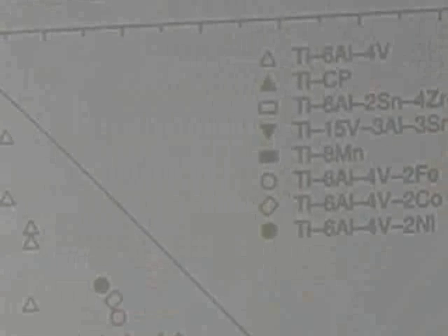So it's harder to get superplasticity in a single phase alloy, okay? But it's easiest to get superplasticity when you have about 30% of one phase inside another, because that 30% phase is completely encapsulated in the second phase, as not exactly spheres necessarily, but something close to spheres.